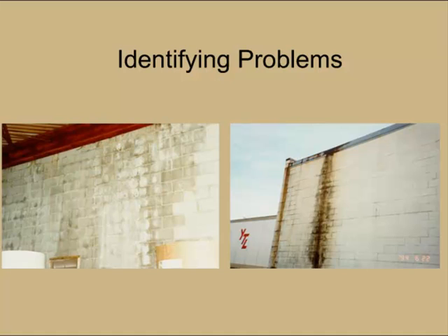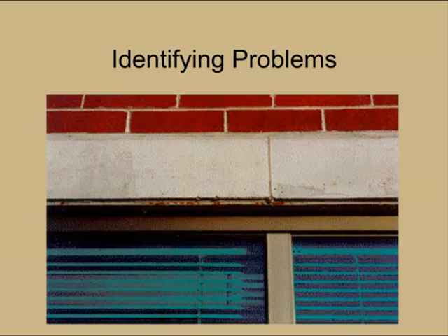Doesn't fail. I get questions on this all the time. But Russ, what is efflorescence staining, and what's the cause of that? Efflorescence is caused when moisture over a long time is moving through the wall, and it's dissolving and carrying some of the calcium materials dissolved in the water. And then as they dry, they deposit it as calcium carbonate or calcium sulfates. This is similar to the process that you see in caves where stalactites and stalagmites are formed. Okay. So that's indicative of moisture in the wall system. Long-term continuing moisture. Okay.